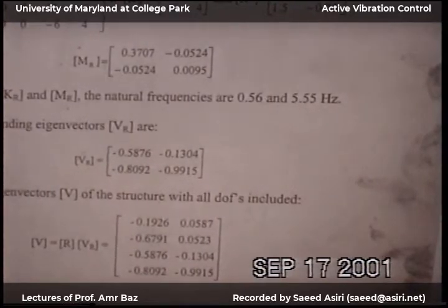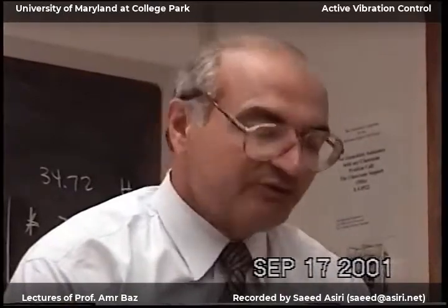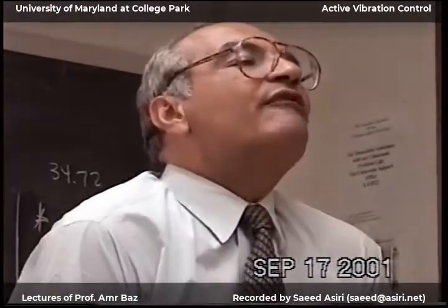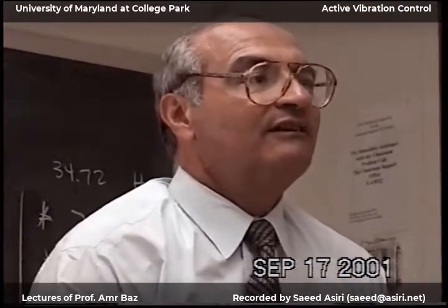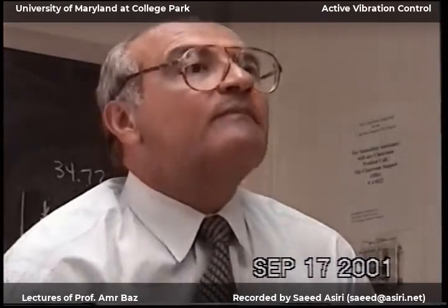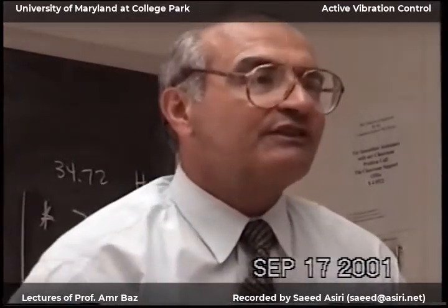If my system, I know, for example, a vibration mount, I want to design to isolate vibration from an engine to the floor. I know the frequencies of the engine. So I want to get the dynamics of the structure to be twice as much as this frequency.